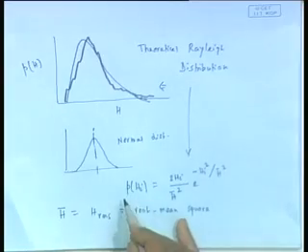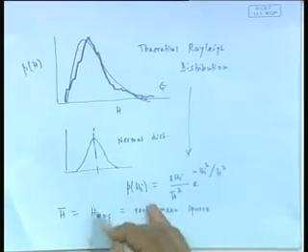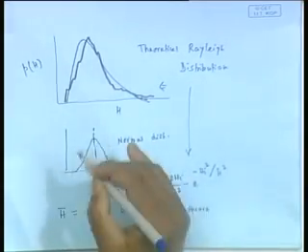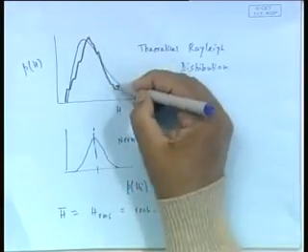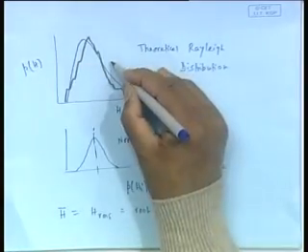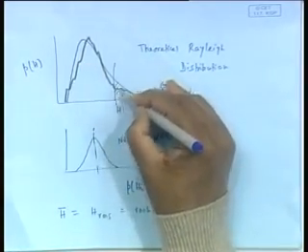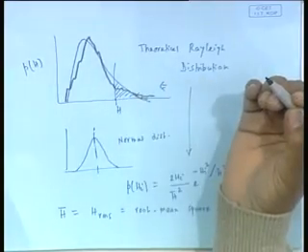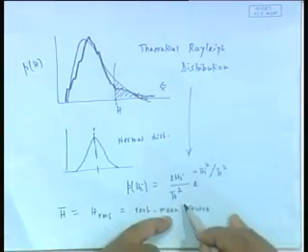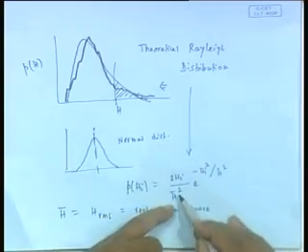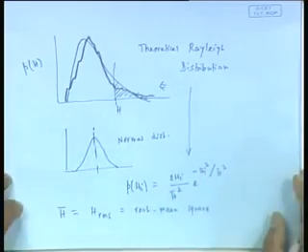For example, if I know P of Hi, I can find out the probability of Hi exceeding H star. That will be just the area from that to this. Supposing I want to find out the probability of wave height exceeding this value, obviously that is this area. So this can be done theoretically from here. I can do it because I know H bar, and all that.